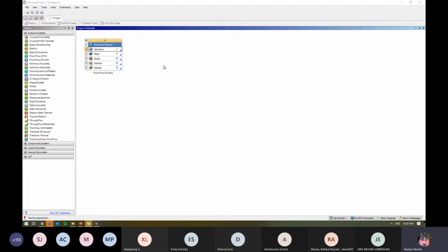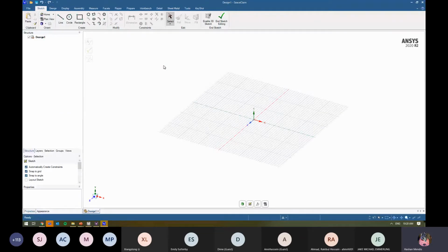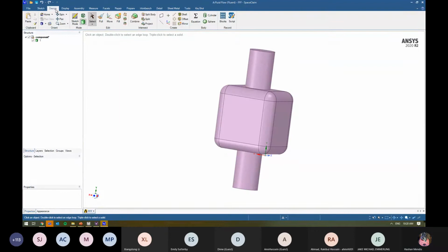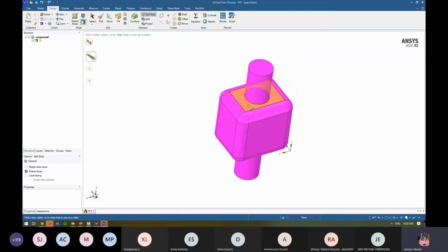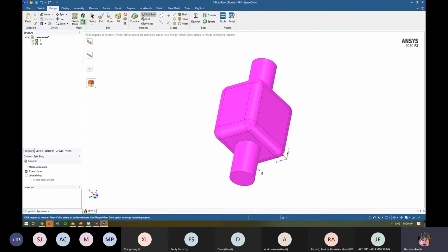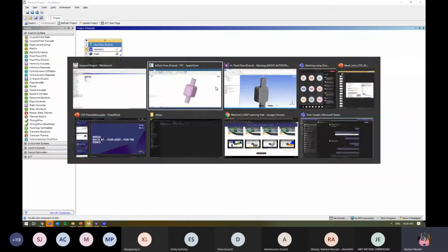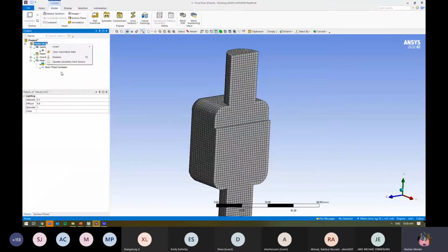Limitations to multi-zone? Yes, sometimes with multi-zones, if the geometry isn't broken up in a specific way, or if it's very complex, the multi-zone algorithm can have some problems actually creating it and generating a high quality grid. So what we might want to do, like I'm doing here, is actually go in, change maybe the geometry or cut it up a little bit, and that way, when we bring it back in, you can play around with it.